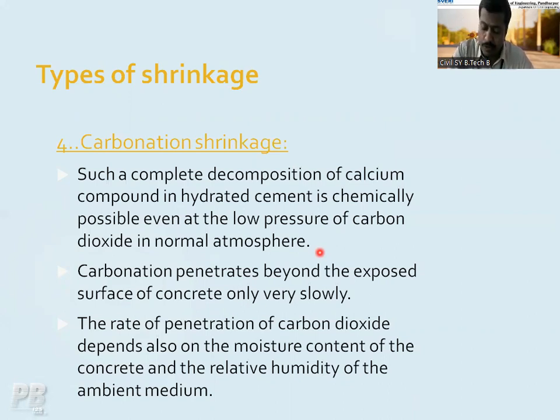So the free CO2, the CO2 which is present in the atmosphere, will react with the hydrated cement. The calcium hydroxide gets converted into calcium carbonate, and during this reaction there is a complete decomposition of your calcium compounds, and because of that there is a change in the volume of the concrete. It leads to the carbonation shrinkage. याला म्हटलं जातं carbonation shrinkage. समजलंय सगळ्यांना? What is carbonation shrinkage?